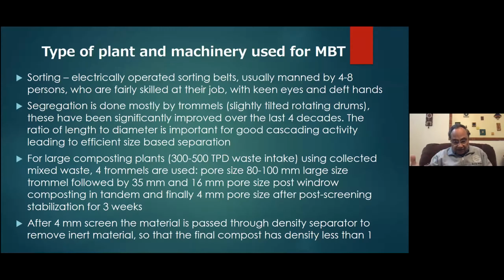My predecessor speaker was discussing a lot about methane generation, nitrous oxide generation, and carbon dioxide generation. We found that if, on average, the material is completely turned once a week, then the composting is better and the unwanted methane generation is much less.